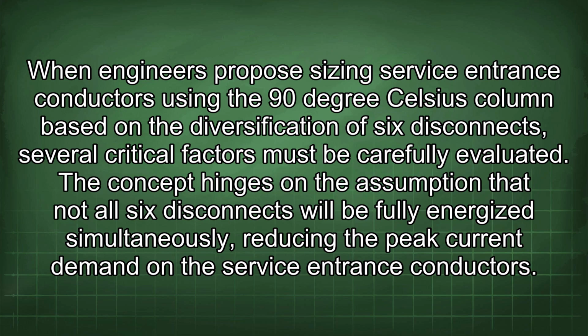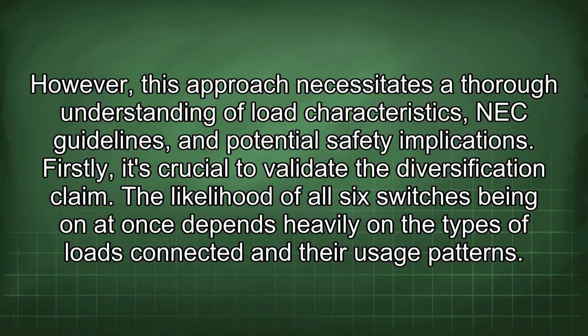The concept hinges on the assumption that not all 6 disconnects will be fully energized simultaneously, reducing the peak current demand on the service entrance conductors. However, this approach necessitates a thorough understanding of load characteristics, NEC guidelines, and potential safety implications. Firstly, it's crucial to validate the diversification claim.